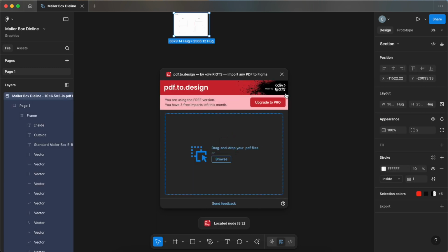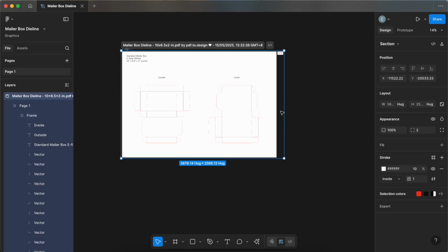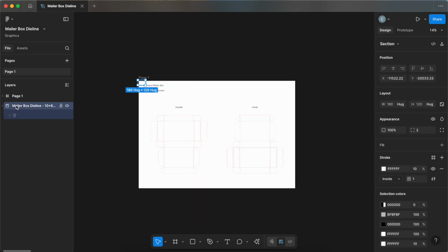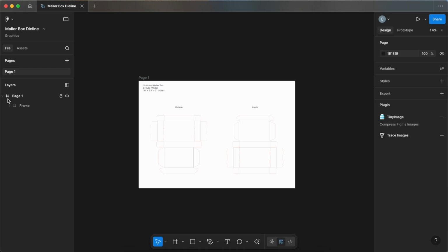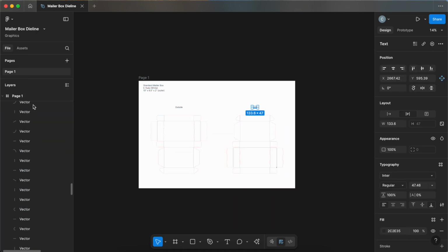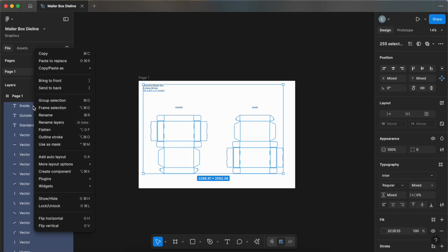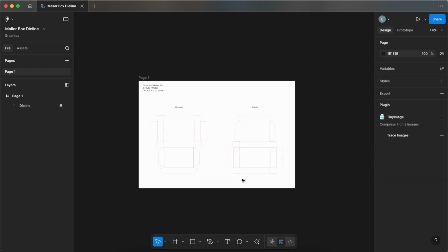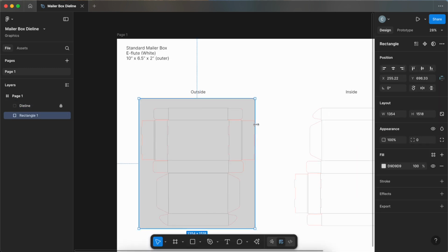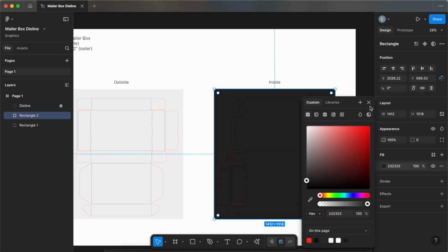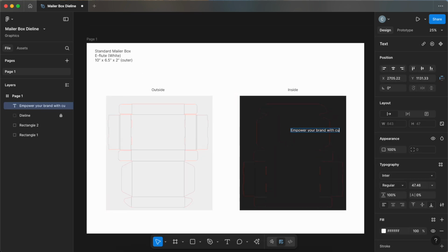To help make the design process easier, begin by isolating the frame with the Dieline by moving it out. The rest can be deleted. Then you can deframe the items inside by selecting Ungroup and then putting them in a group for ease of use. You can reference the appropriate Dieline design guide to help navigate which panel is for which side of your box. In general, it is good practice to reference guidelines for Dieline design.